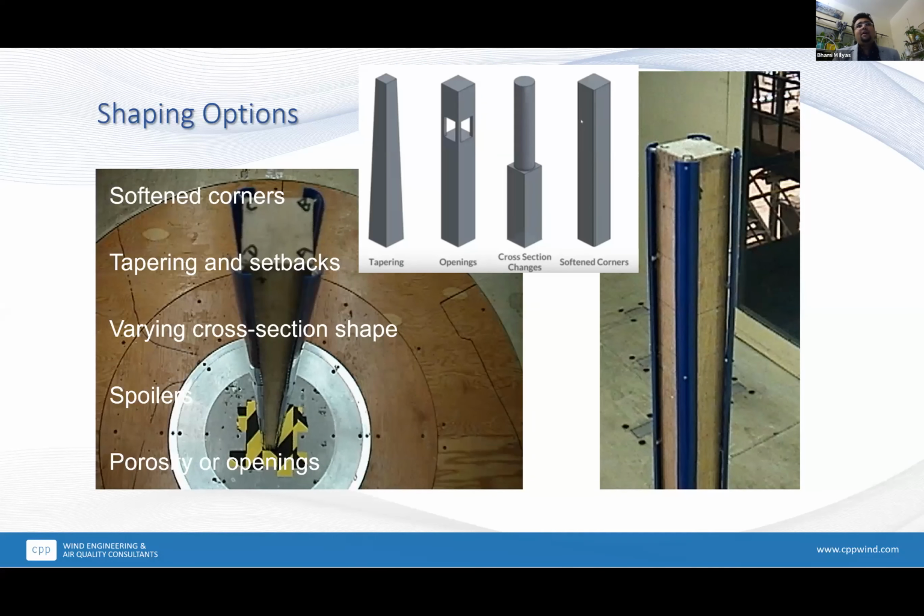Interestingly, we find out that some of the buildings, we really have to work on the exterior, the architecture of it, and we have to come up with solutions to try to dampen the wind. And how can we do that is a different process of playing with the form, the exterior of the form, and this is where we and architects go to the drawing board to see where we can cut down the loads that are governing the design, the wind